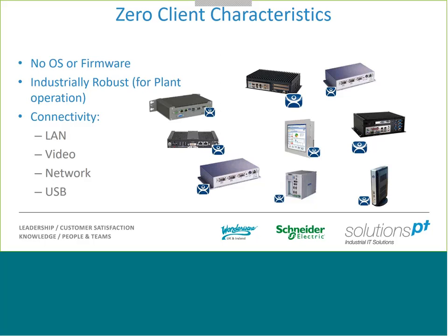And if you suffer a failure with Thin Manager on one of these devices, the application is running on the terminal server, so that will continue to run. You're not suffering downtime. You've lost the visibility element of that process until you very quickly get one of these clients replaced. Whereas in a thick client solution, if that PC dies, then you're suffering downtime from the off.